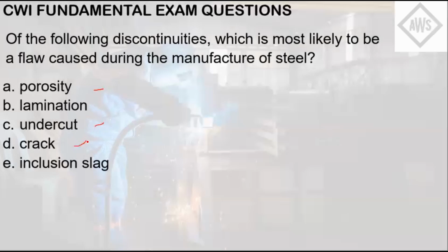A crack is a serious defect that can lead to failure. As you know, there are no acceptable forms of crack. If you see it, it's automatically a defect. Slag inclusion is the inclusion of a material in the weld metal. This can commonly be formed when there's not enough cleaning in the weld. So for letter B,